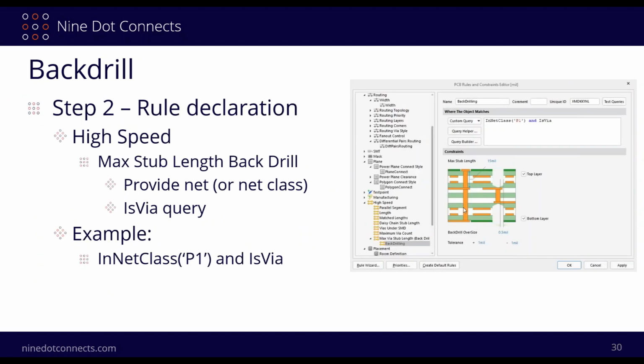All right. The second thing I have to have is a high-speed design rule. Why is that? Because back drilling is not a property of through holes, and that was what was driving me crazy when I was trying to get this to work. It really is a primitive all its own, but it is driven only through the declaration of the layer pair, and it is driven through a rule. So there's no way you can really click on a back drill and look at its properties. It has to be driven all through a rule over here. It's kind of like a room if you think about it, right? If you dealt with rooms in Altium Designer, yeah, you can click on it, but most of it's driven by the rules. Here, the back drill is strictly driven by the rules.